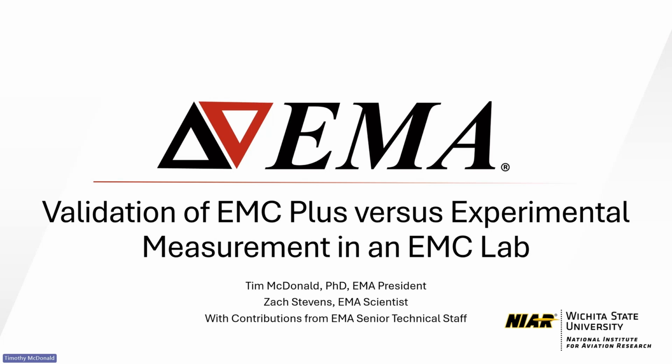What we have been able to do, with EMC Plus, connecting the cable harness to the printed circuit board, is measure what are called mixed mode scattering parameters for differential mode to common mode conversion. And we have been achieving excellent correlation of that conversion scattering parameter a priori, totally with simulation of that line. So all of the black magic of some stray capacitance happens and we get the conversion is replaced by quantitative prediction that you can then plug into your SPICE models of your power system.